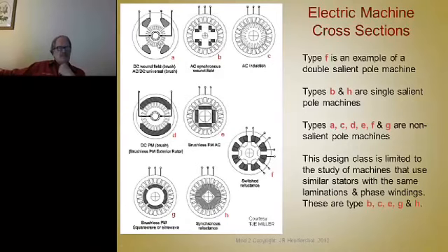So rotation is continued. If you reverse the polarity of the voltage across these two terminals or across these two terminals, you change the polarity of the flux generated by either the stator or the rotor. If you have permanent magnets here, then you just change the polarity of the armature. Now, what's interesting to note, even by looking at this picture, is down here we have a permanent magnet version of this. Here's a permanent magnet version of that.